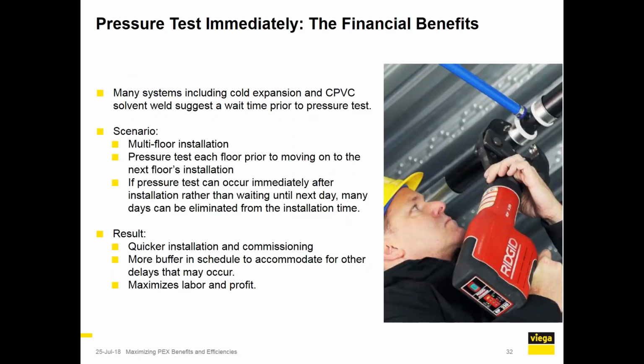Another financial benefit, our fitting is able to be pressure tested immediately. Other fittings such as cold expansion or CPVC solvent weld cannot be pressure tested immediately. And those wait times vary from system to system. Some of them range up to 24 hours even. So imagine another scenario, a multi-floor installation where you're installing every single floor, but you do one floor and then you pressure test before moving on to the subsequent floor.